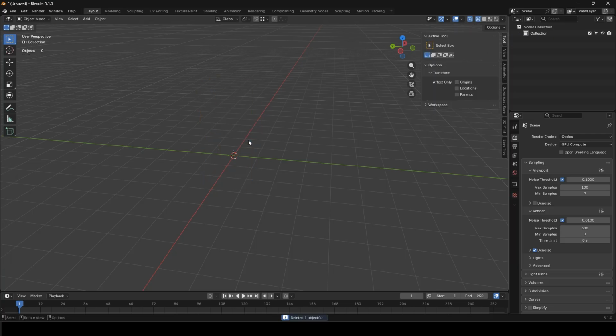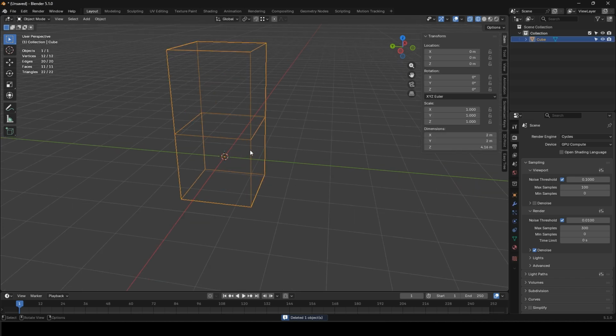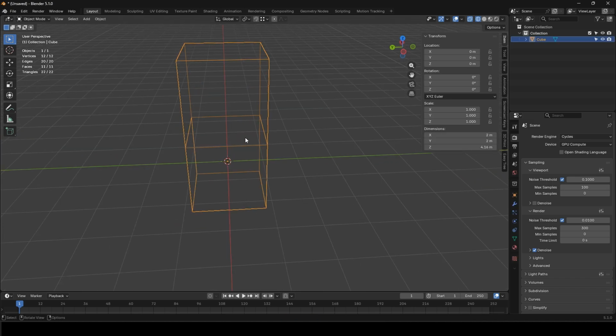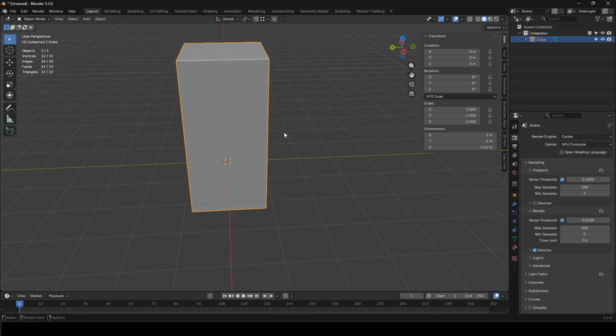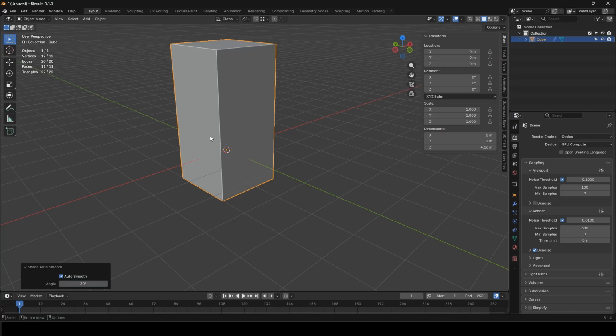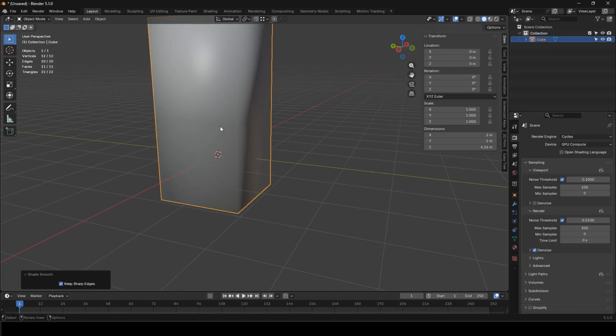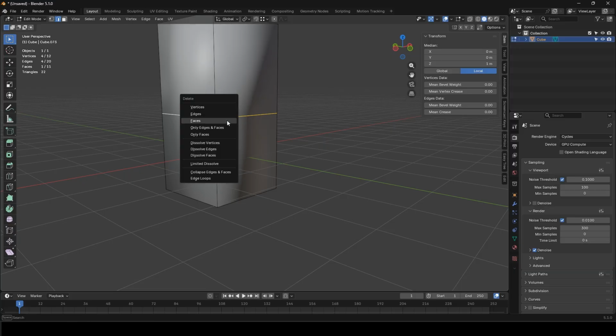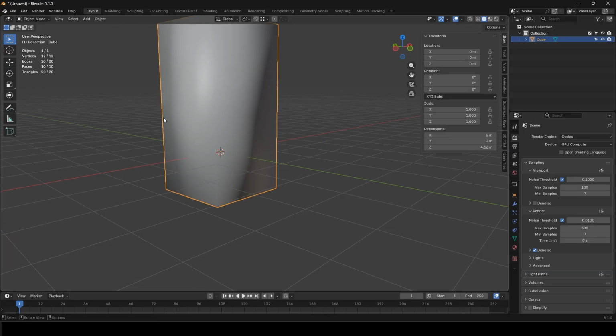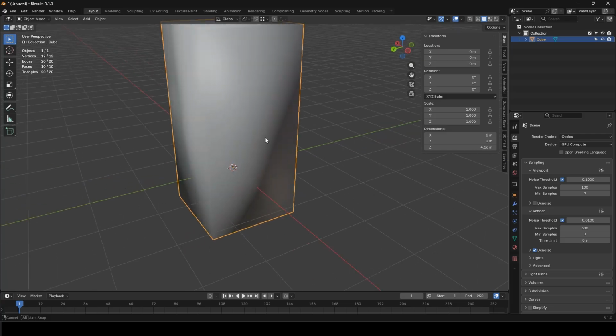One example of doing that is if I was to use the mirror modifier, which I'll show you in a little bit. But basically what we've got here is a face, and if we go back into our regular shading and turn on shade smooth, we'll see that we get this sort of kink. So if we were to delete that face, our shading becomes a little bit better.